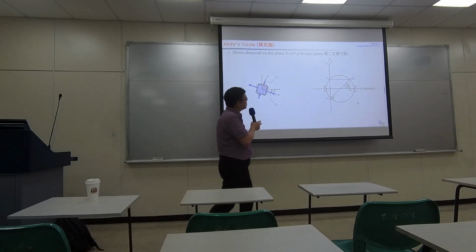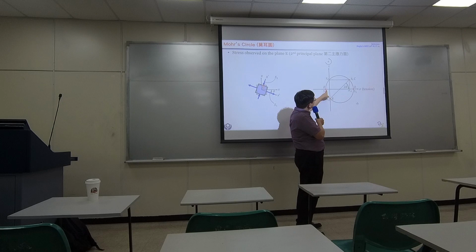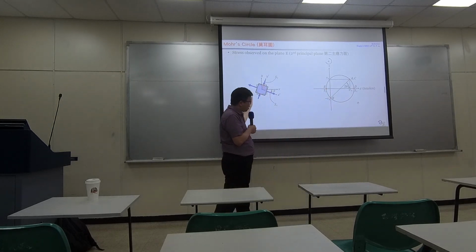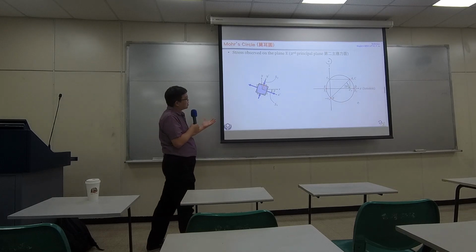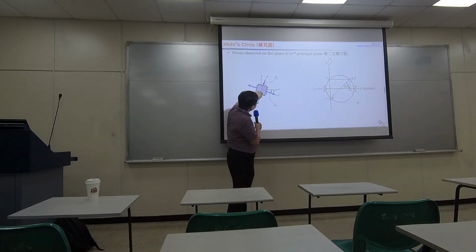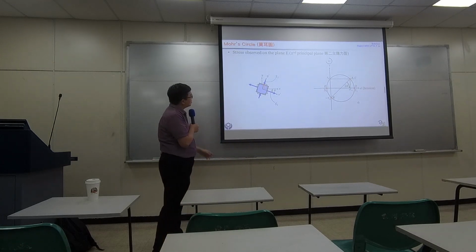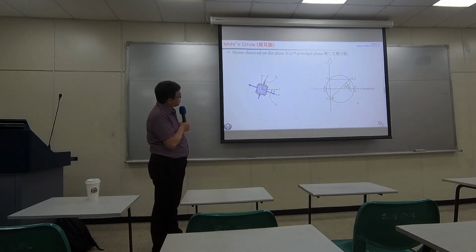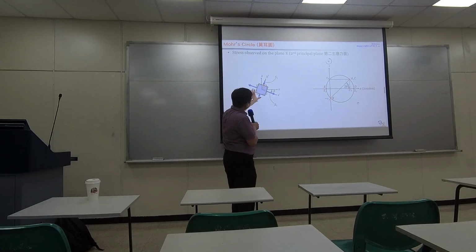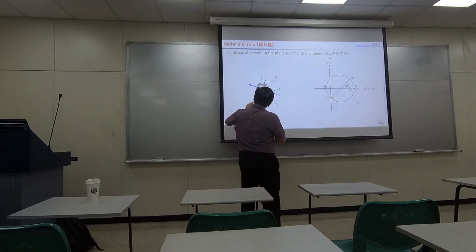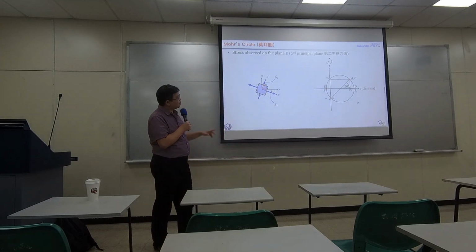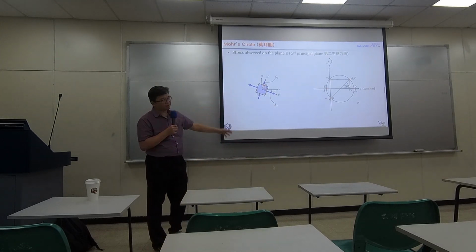It turns out the second principal stress ends up on the left-hand side of the coordinate. It's a negative value. That means there is compression along that second principal stress direction. Okay? So that completes the free body diagram along this principal axis. And you can tell there's no shearing stress.